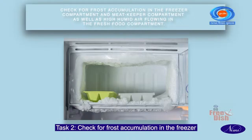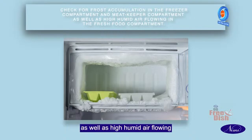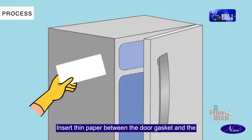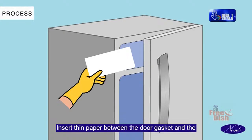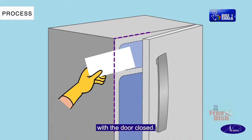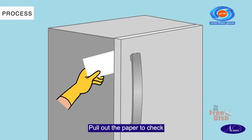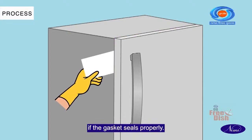Task 2. Check for frost accumulation in the freezer compartment and meat keeper compartment, as well as high humid air flowing in the fresh food compartment. Insert thin paper between the door gasket and the gasket sealing area on the body of the refrigerator with the door closed. Pull out the paper to check if the gasket seals properly.